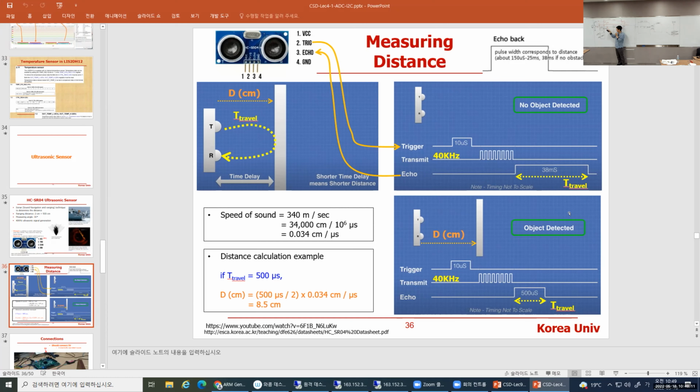The protocol is to clear that bit, in 2 places. You program the end of interrupt register, and you clear the status register.